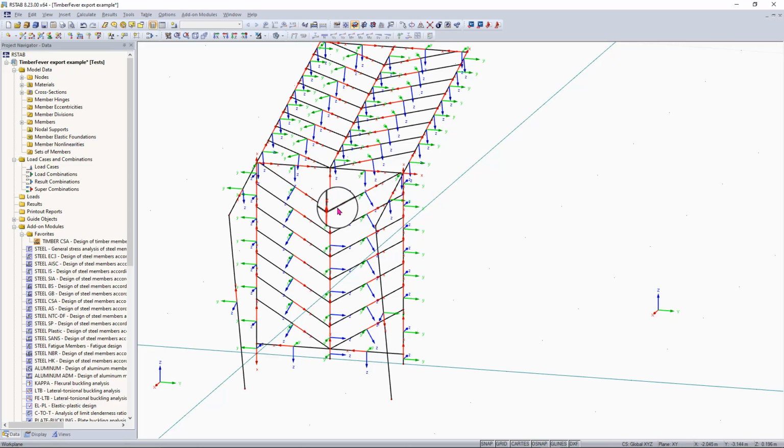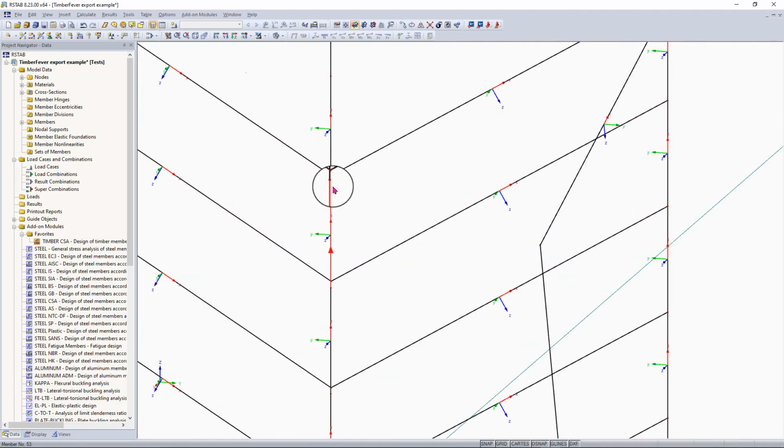to fix this, the simplest way is we can just go through and delete our lines here. And now that our lines are deleted, we can simply select this line here, and then we can hold Control and drag, and that will drag and copy our line. And then we can do that one more time. And now we have that same line, and all the axes are in the same orientation.